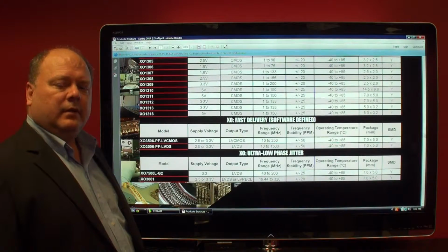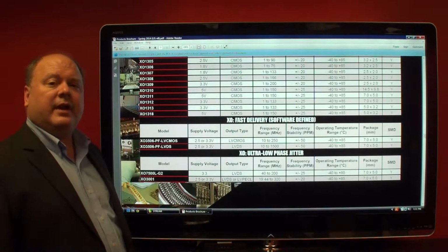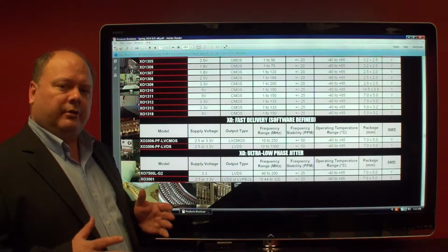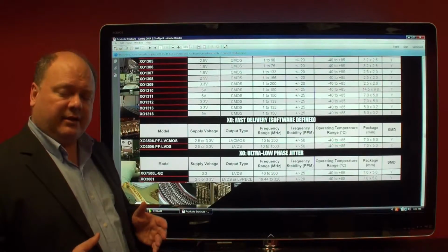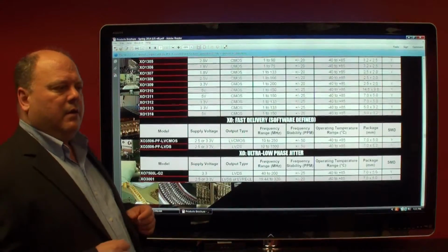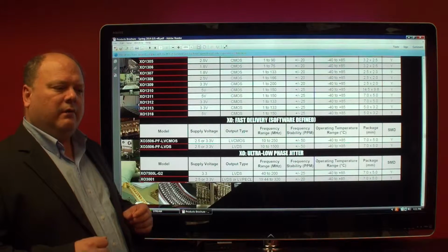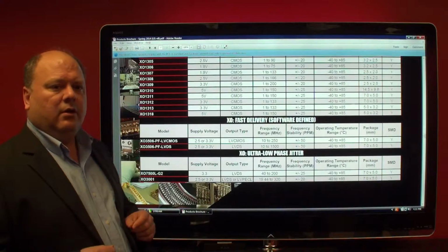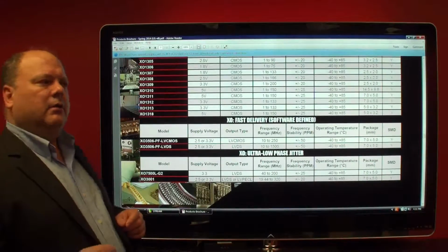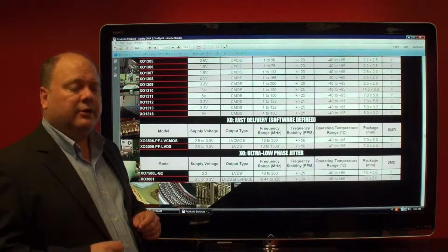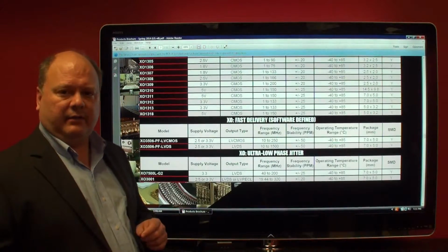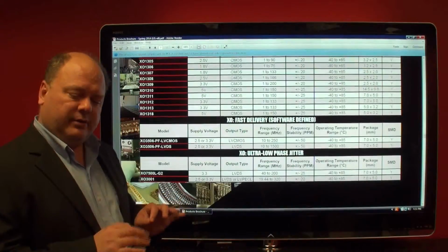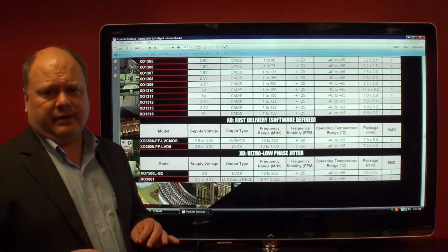Good afternoon. Today I want to talk about, as part of the 2014 Dynamic Engineers product catalog, ultra-low jitter, ultra-low phase noise XOs and VCXOs. This is a niche in the market that generates the best selling prices for any of the oscillator companies. Ultra-low jitter means less than 1 picosecond integrated phase jitter, from 12 kilohertz to 20 megahertz offset frequencies.